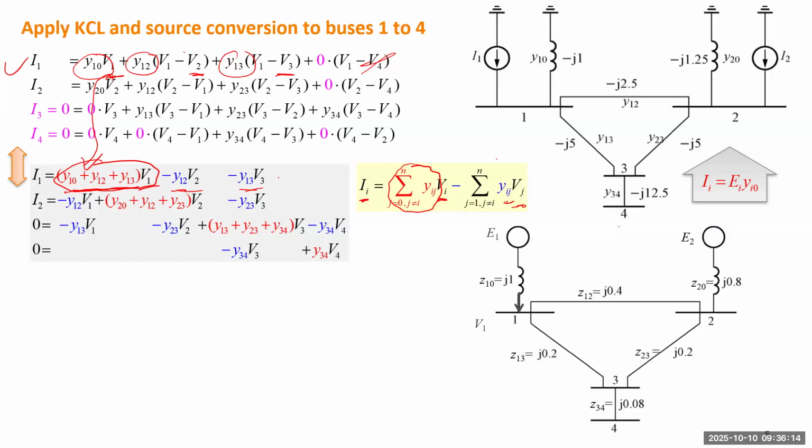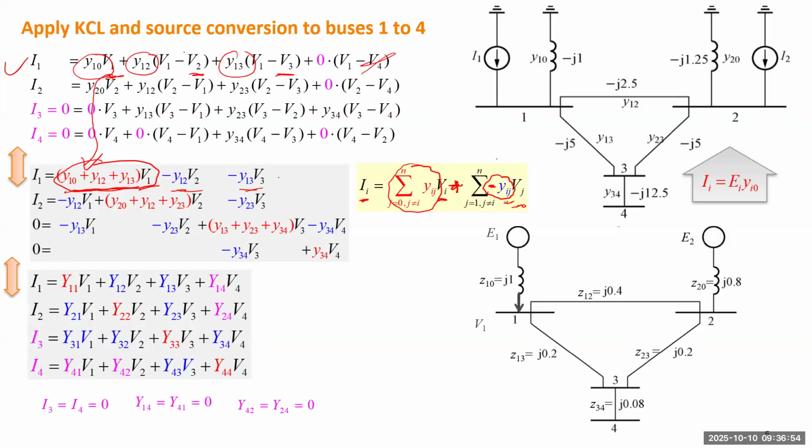And also there's a negative sign. If you move this negative sign inside, the second type of item is the voltage of any other bus multiplied by a negative admittance from that bus to this bus. So this is the second type of standard form. We don't want to memorize this equation. Actually, you need to memorize it anyway later, if you want to solve problems. But for now, we want to find an even simpler form for this second type of equation. Let's just go ahead and give it the standard form.